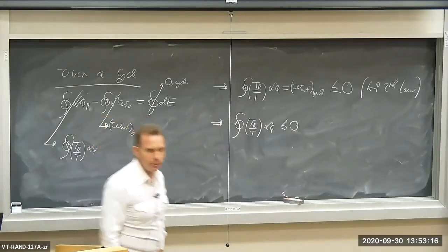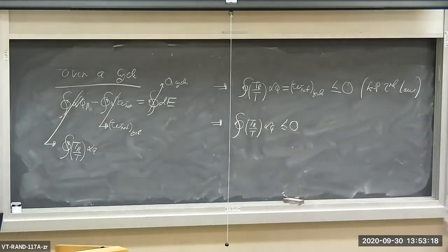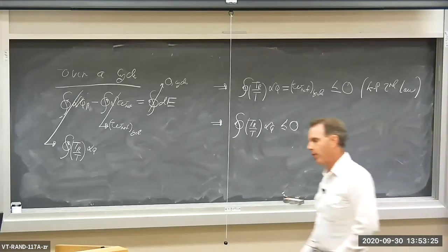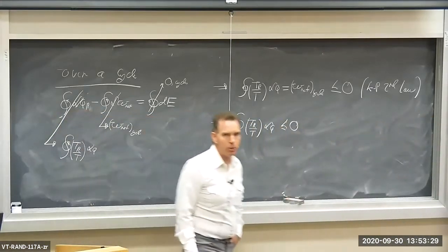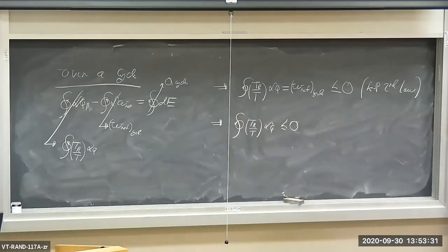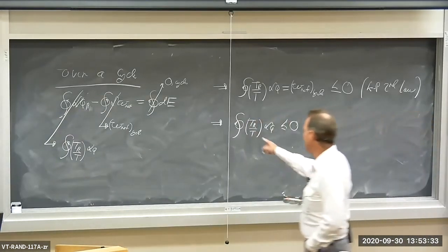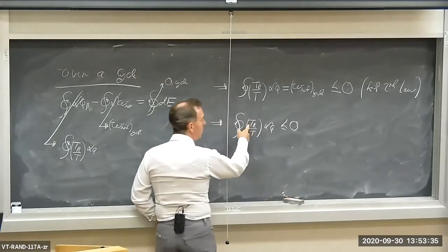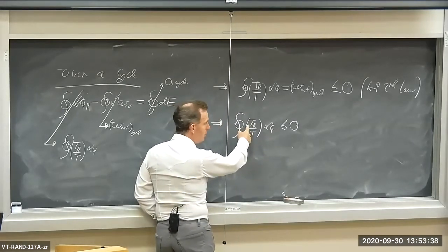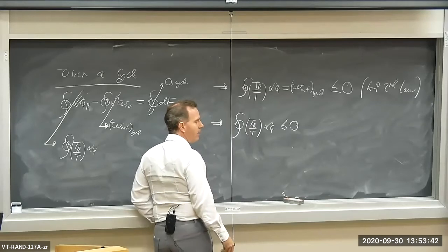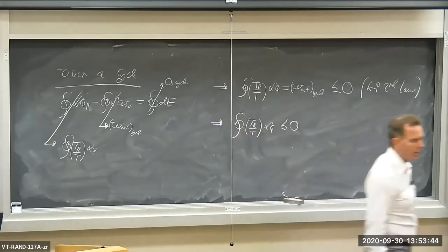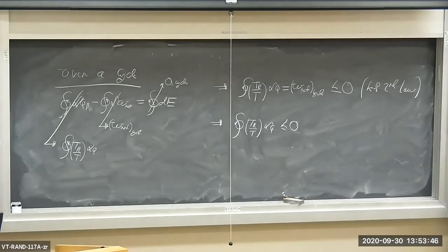Now, one last little step before we finish up. The reservoir temperatures are in absolute terms. They're in Kelvin or Rankine. There's no such thing as a negative absolute temperature. The reservoir temperature is constant, so I can extract it out of the integral, and then divide both sides by the reservoir temperature to get rid of TR.